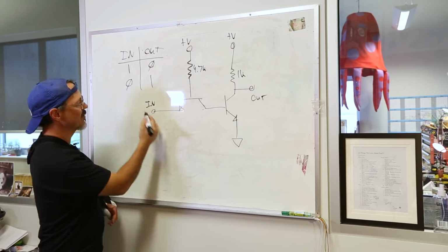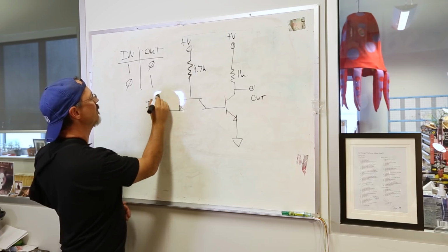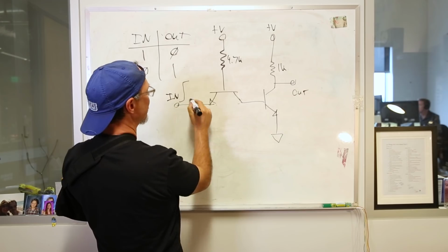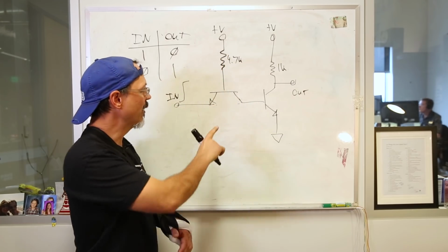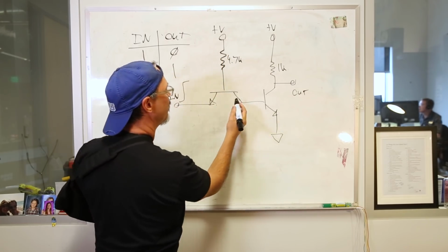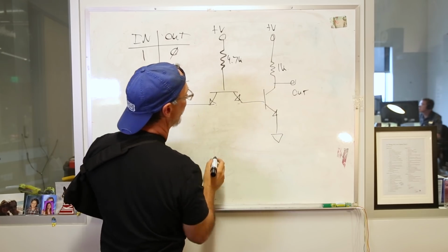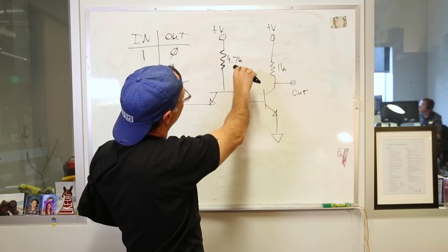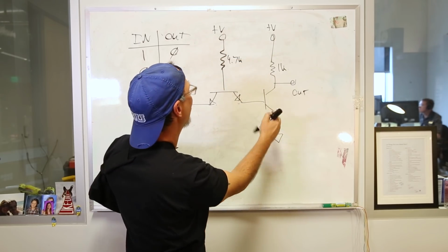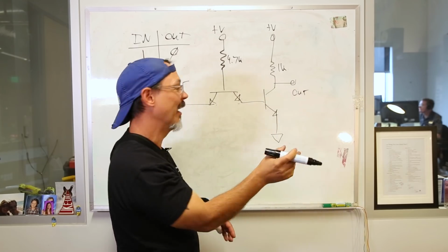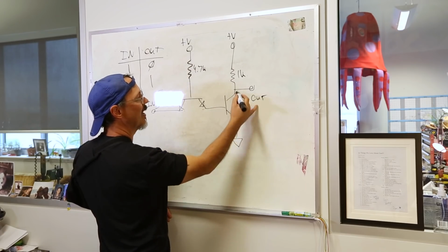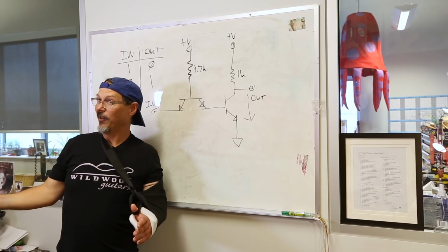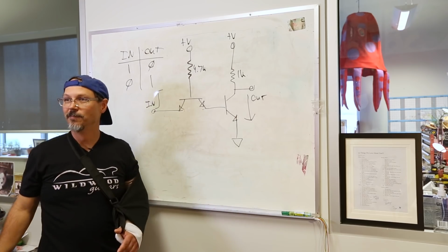In the opposite direction, it does something kind of cute. Okay, so that was low. Now, if we pull this input high, check this out. This junction turns off, right? So this is a plus V. Now, remember, this is a BJT, which is effectively another diode, all right? So what happens is you end up with positive voltage, resistor, diode, ground. So this guy turns on, all right? And when this guy turns on, this becomes a low resistance and your output goes low. Pretty cool, huh? That's an inverter.